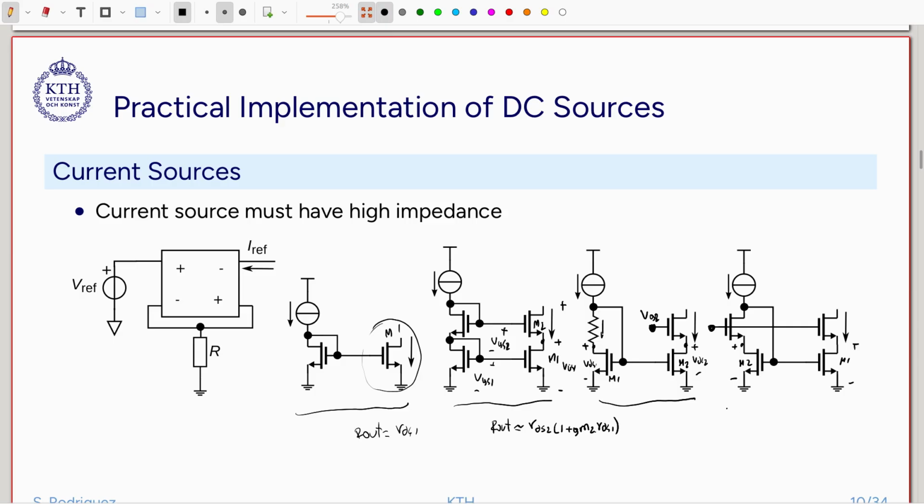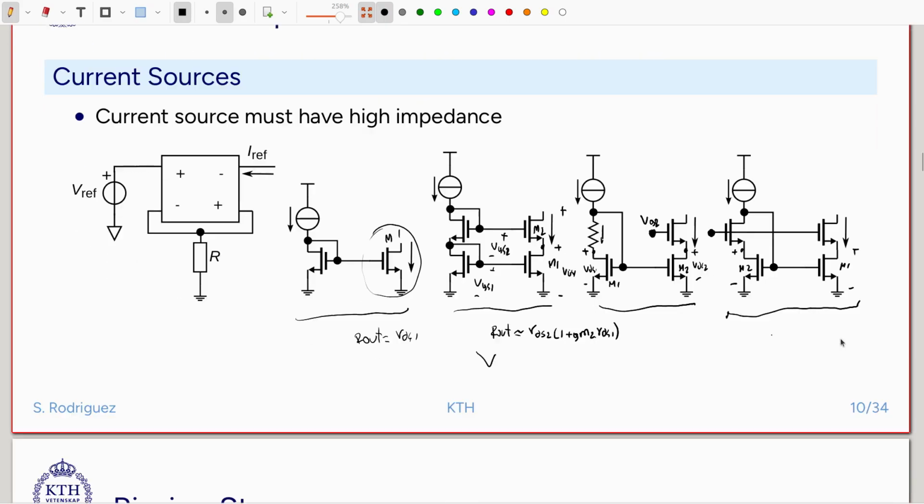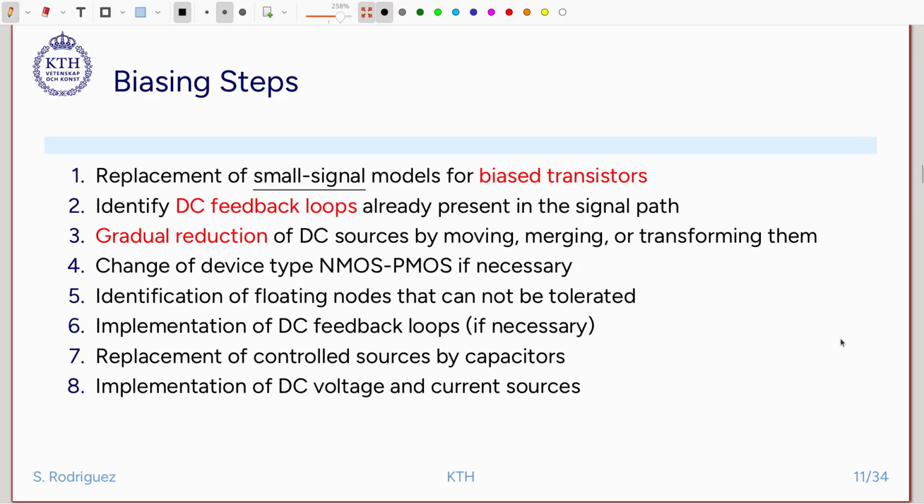Very often this is what we will be using. There are very few cases when I will probably use the alternative here. The disadvantage of this one is that you need to generate another voltage here. But otherwise this will allow much higher voltage swing at the output, which is valuable in low power applications.